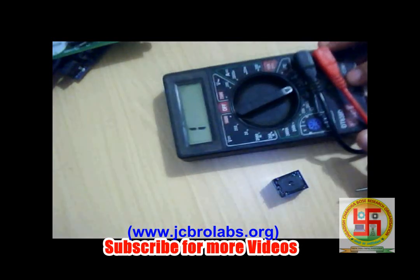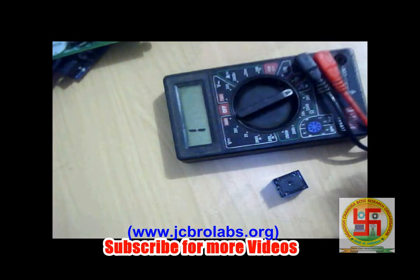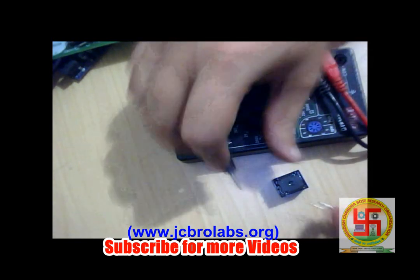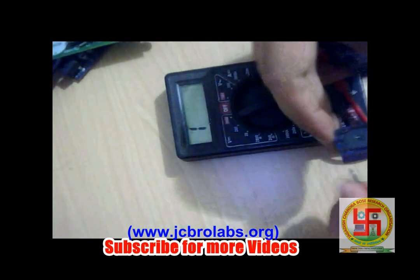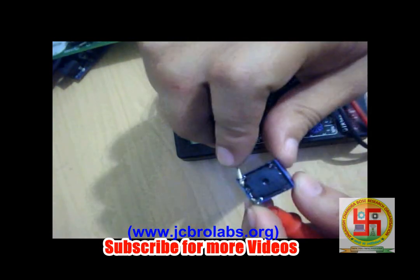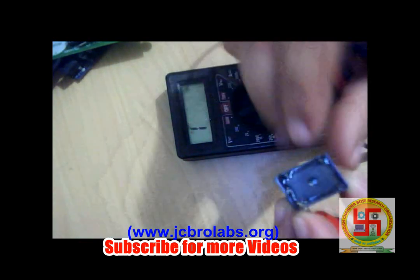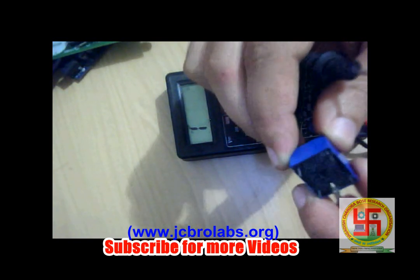The continuity test means we set the multimeter to the beep sound setting, and when we make a short circuit, it produces a sound. So we check pin by pin and see which pins are connected right now. If we check these 2 pins, the end pins, if these are visible. Okay, so there's no sound. And let's check this middle pin as we have discussed in theory.